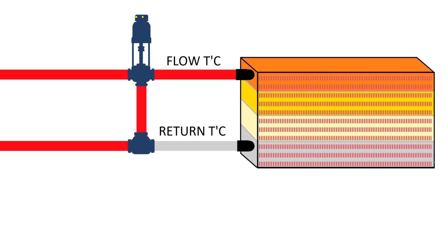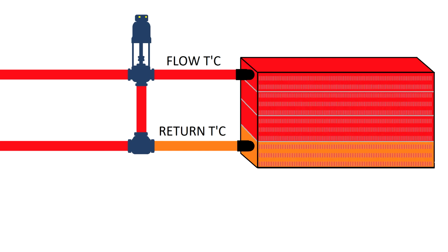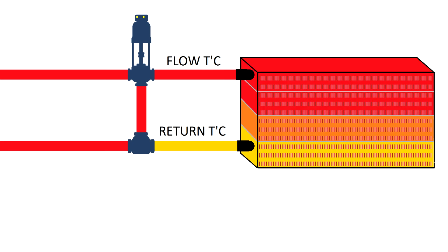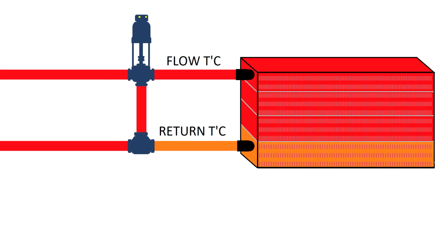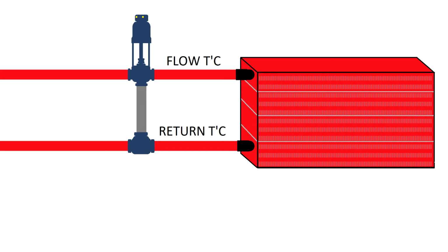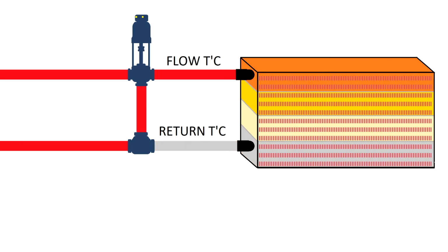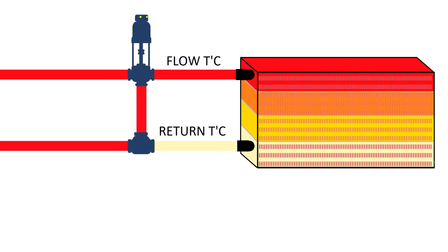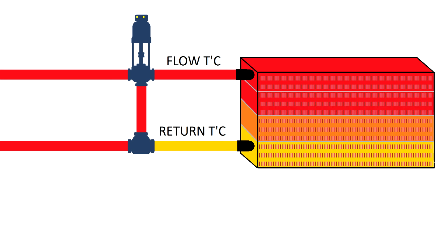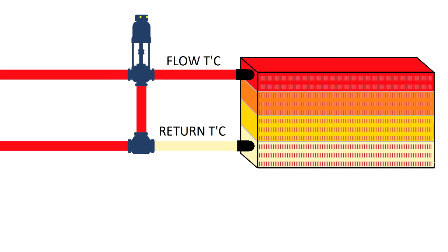Because can you imagine if you have a variable flow before the three-way valve, then the three-way valve tries to control a flow which is already variable, and that's a nightmare. So the temperature must be constant and the flow must be constant before the three-way valve, so the actuator will control the heat exchanger's capacity properly.